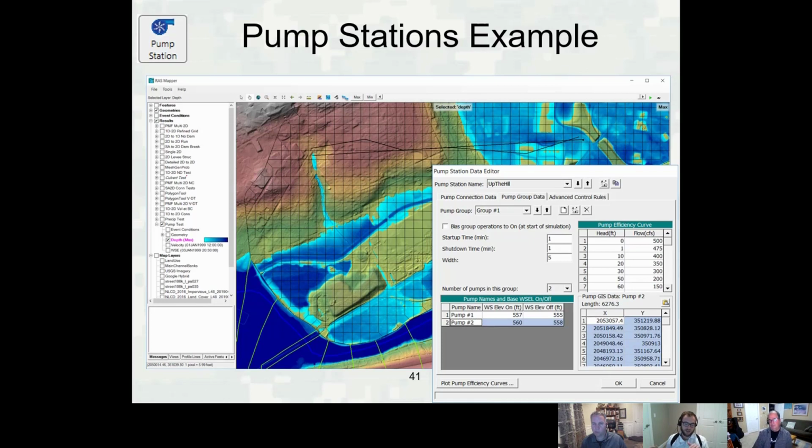Is that a similar thing to note when you are connecting pump stations to individual 2D cells, to make sure that the cell you're connecting it to is not too small in regard to perhaps the peak volume that is going to be withdrawn from that cell? Yes, you need to think about that, and that can happen, and there's ways around it though. However, it's not going to be near as bad as with the SA2D structure and the Weir equation. Other problem with the Weir equation is not only the volume in the cells, and it's not that it can't handle the small cells, it can.